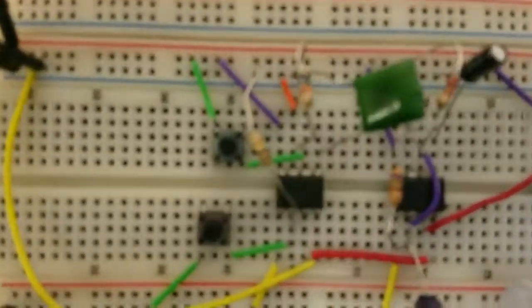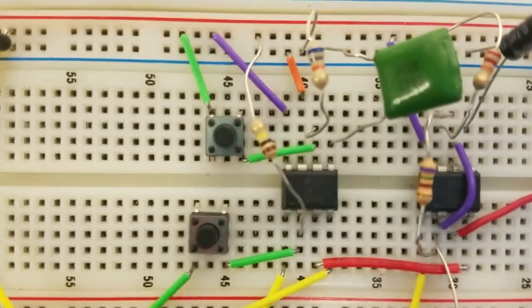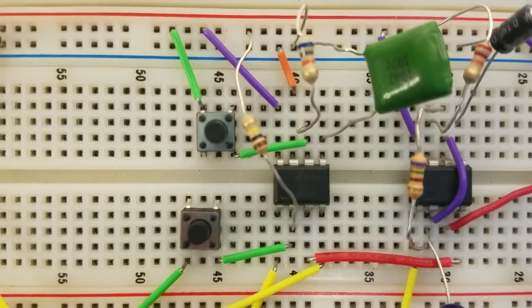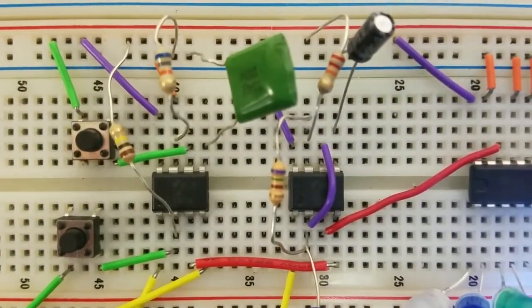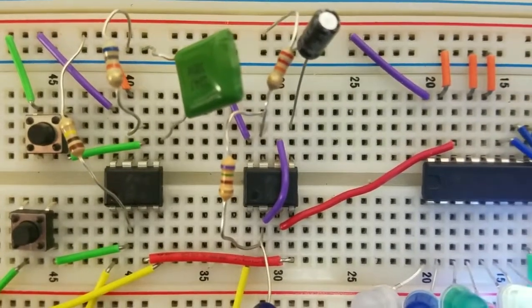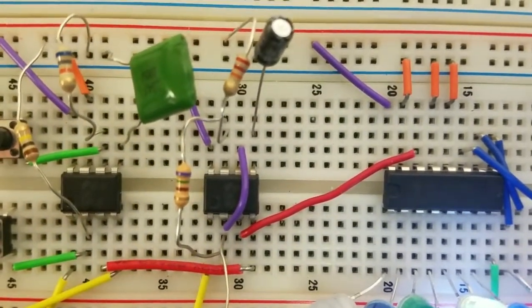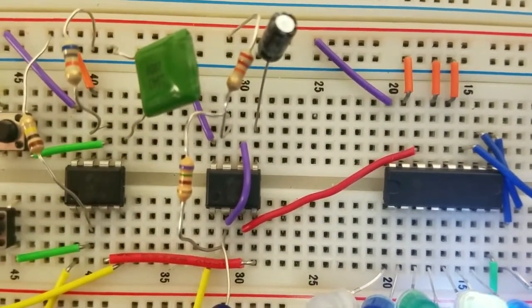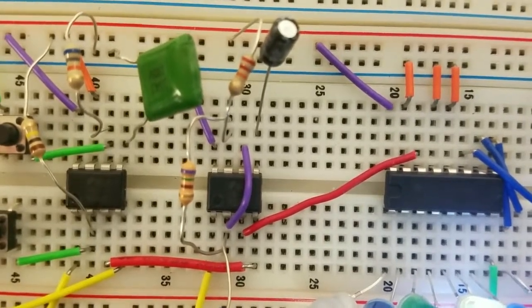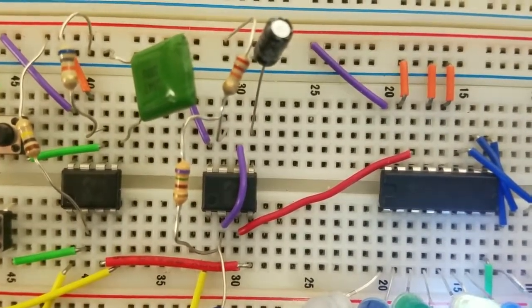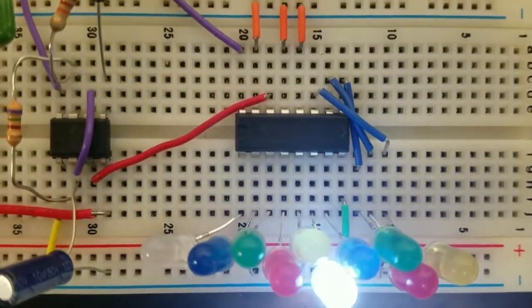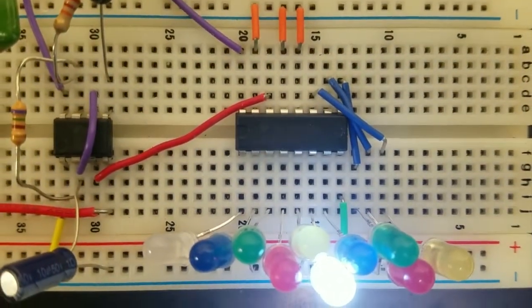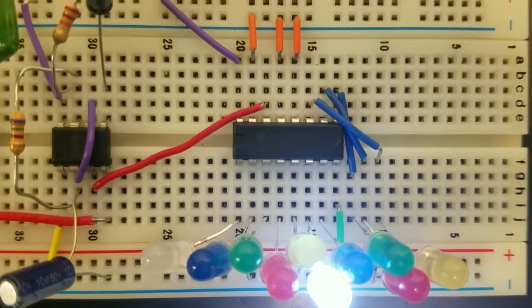It is important to note that in order to implement the switches, there must be two 555 timers. This is because when the bistable timer is logic high, the astable timer will oscillate and therefore change the decade counter based on the output of the RC circuit. When the bistable timer goes logic low, it resets the astable timer, holding only one LED on. It doesn't turn off the LED because there is still power connected to the decade counter.